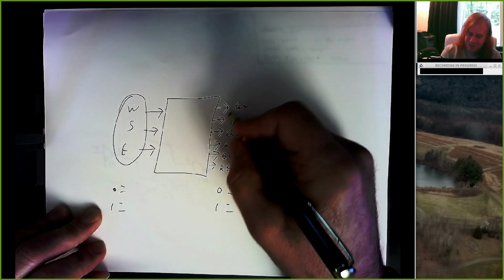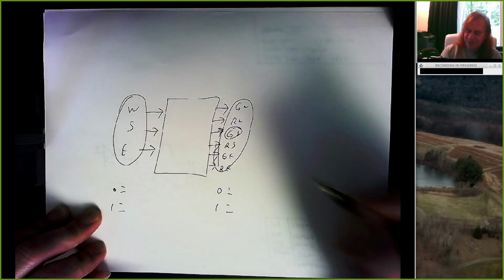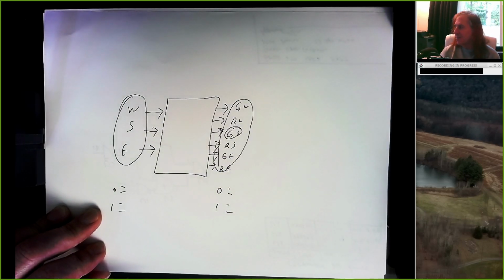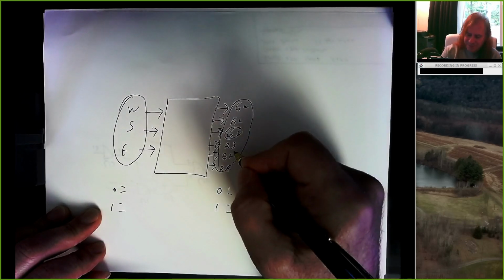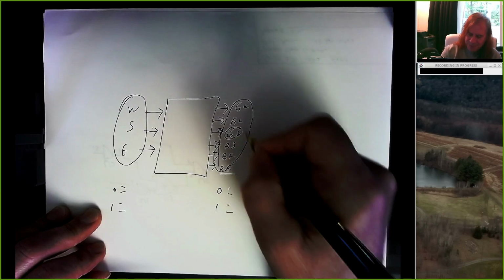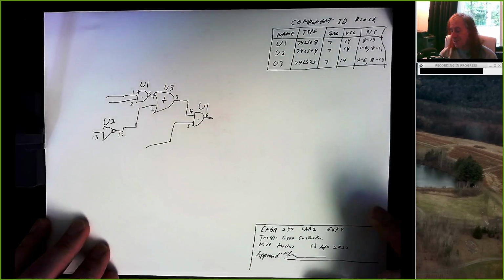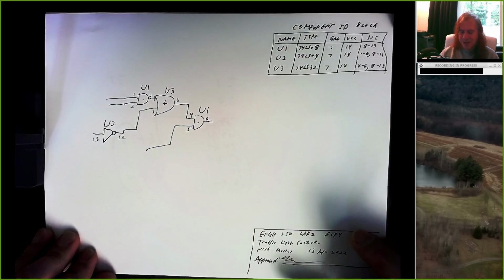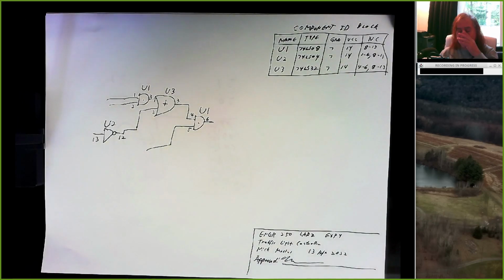And when you look at your LEDs, right, if this output is a 1, this LED, which you'll use a green LED for, should turn on. And all these other green LEDs should be off, and these red LEDs should turn on. And so when we're testing our circuit, and eventually when we're using it, we don't want to just take a multimeter and say, is this 5 volts or 0 volts? We want to actually have switches for the inputs and LEDs for the outputs.